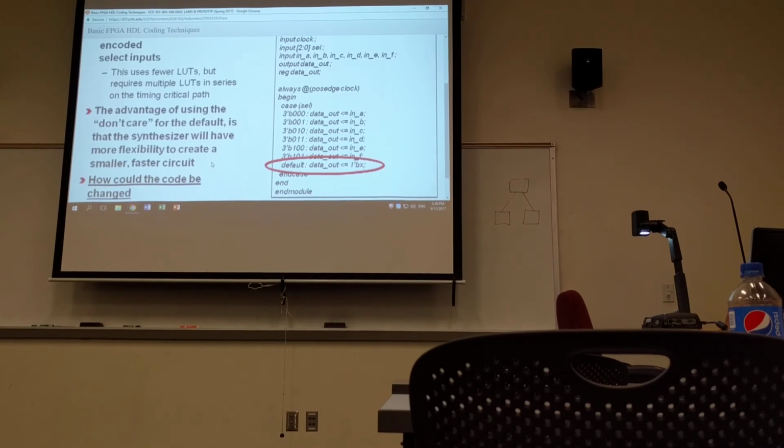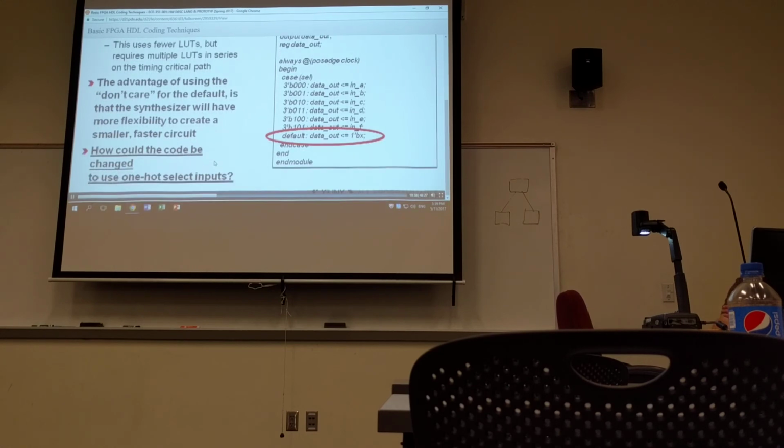This example shows a 6-to-1 multiplexer with binary coded inputs. Notice that a default value has been defined for the remaining possible combinations of select line values. This makes the implementation much smaller. XST used not only LUTs for this design's construction, but also took advantage of the dedicated muxes included with each slice. These muxes allow larger multiplexers to run faster and save LUTs. In this case, the result used fewer LUTs and got better performance by having the dedicated muxes available.